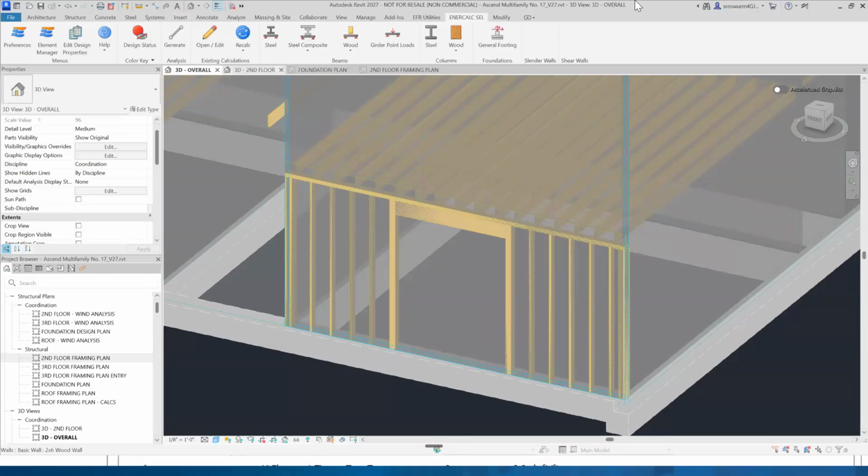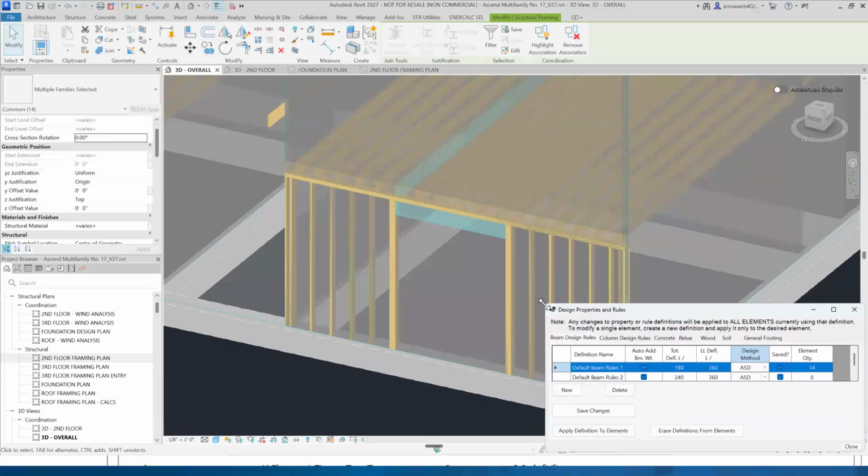Yes, please. I have a question here from Stephen. Your design for the general footing seemed to have an allowable soil bearing stress that was different than the needed soil bearing stress. Seth, I don't know if you want to pull that calc up or if this is something we might want to take offline. No, that's a great question. All of those assumptions you can control in the same way you could a normal manually built calculation. And if you do make changes, like changing the allowable soil bearing, those changes will interop back here to your design properties window.